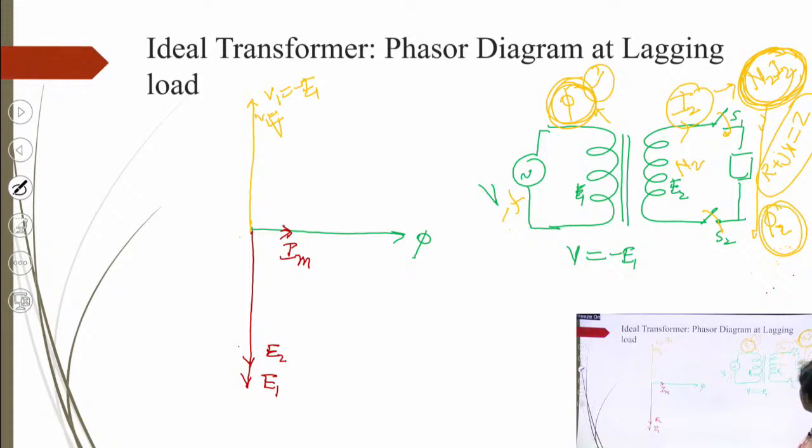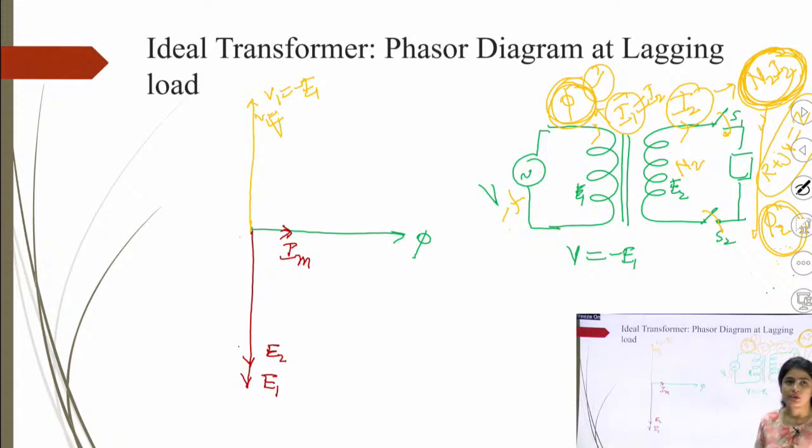So as the load is connected, in the primary side another current, I1 dash, will flow, which is equal to I2. This I1 dash multiplied by N1 will produce its MMF, which nullifies the effect of the load. Thus the transformer will contain only the flux phi.